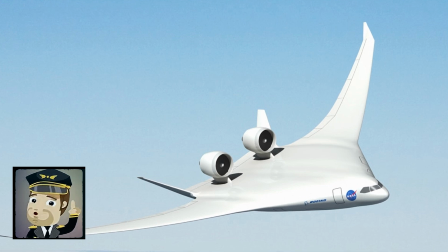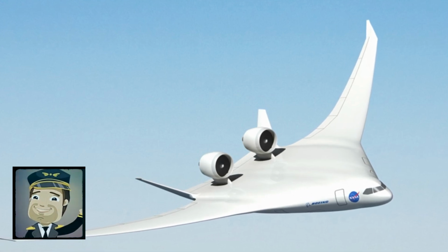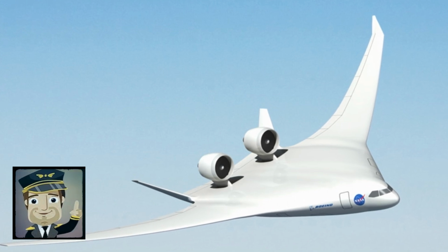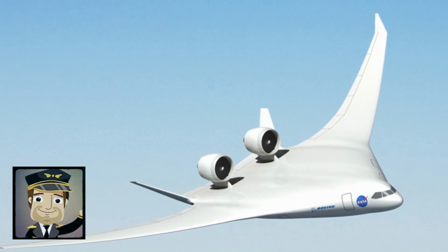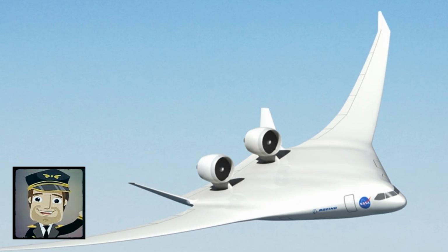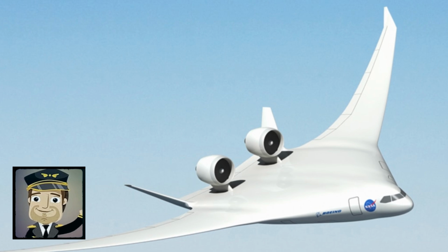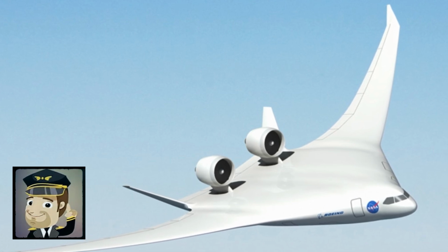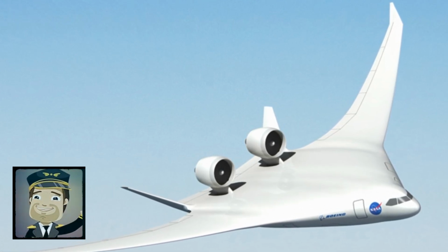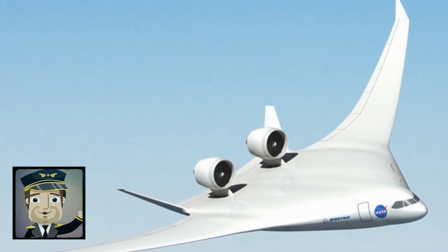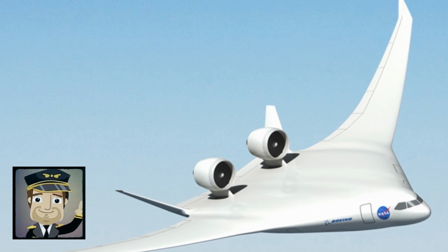The engine cores are shrinking as they operate at higher pressure ratios and become more efficient and smaller compared to the fan as bypass ratios increase. Blade tip clearances are more difficult to maintain at the exit of the high-pressure compressor, where blades are 0.5 in high or less. Backbone bending further affects clearance control, as the core is proportionally longer and thinner, and the fan to low-pressure turbine drive shaft space is constrained within the core.